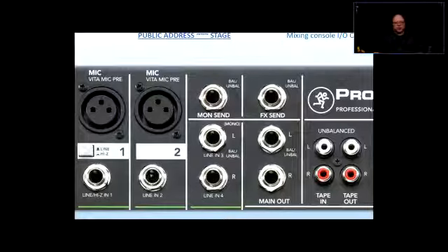The decibels. Okay, when it comes to power of a signal, if you raise the power of the signal by 3 decibels, you're doubling the power. If you lower the signal by 3 decibels, you're cutting the power of the signal by half. Right? So the pad that is there takes the signal down 20 dB, 20 decibels. So that should give you some sort of imagination of how much the signal is being brought down.